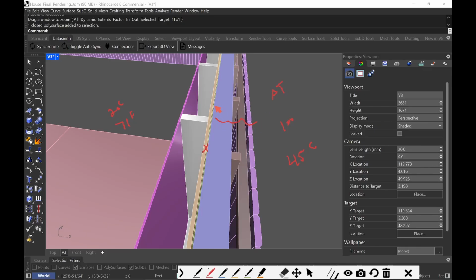Going especially from this rigid insulation, they're saying that at this point here, it's going to condense a lot because you don't have any cavity insulation to taper down that change of temperature. So that's why some people say you need to put in some cavity insulation so that the change of temperature, let's say this is high and this is low, is not abrupt, if you're going to graph it out. We'll say this is very high.